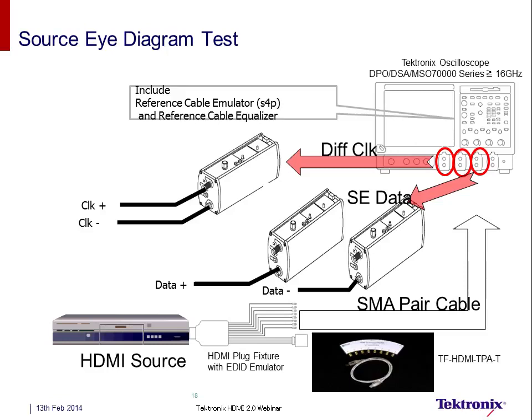So you have to perform the eye diagram test for the remaining two lanes in a manual method, that means one after the other. There is a potential possibility of leveraging this to be automated using an RF switch. Look out for an alert from Tektronix as soon as that feature is made available. The unused lanes can be terminated using a bias T and pulled up to 3.3 volts. We also provide a very easy way of doing that with a termination board which is available from the Tektronix ordering system.